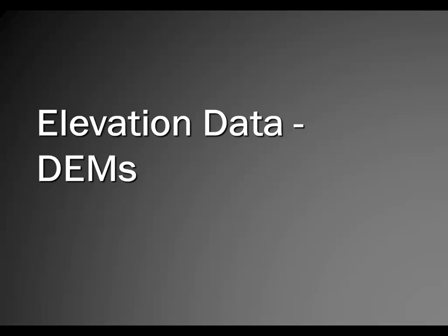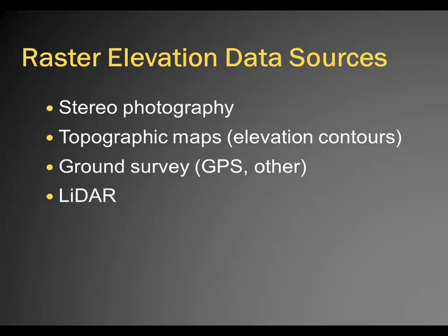Now, the implementation that we need to understand thoroughly for the later workshops is the digital elevation model, DEM. It's a raster, a special raster that just stores elevation. So in each cell it says how high it is above sea level and the location of that cell.